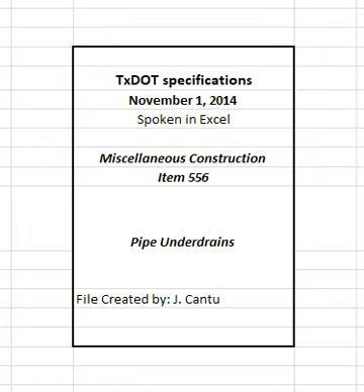2.1.5 Type 5. Acrylonitrile butadiene styrene, ABS, pipe conforming to ASTM D2751, SDR35. Perforations must meet the requirements of TxDOT M278. 2.1.6 Type 6. Corrugated polyethylene plastic tubing conforming to TxDOT M252.